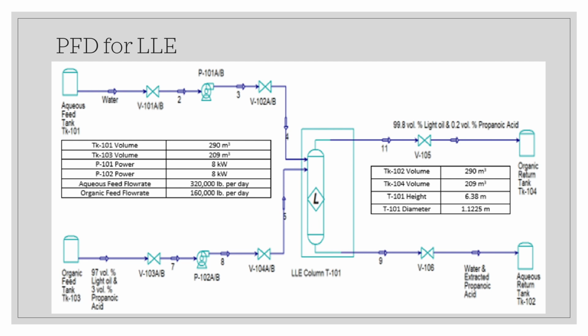In a packed column, one liquid phase is the continuous phase, and one is the dispersed phase. During operation, the continuous phase fills most of the volume of the packed column, while the dispersed phase flows through it in droplet form. Literature sources and experimental results suggested that an aqueous continuous phase produces a better separation than an organic continuous phase, so the aqueous phase was used for experimental trials in this lab.